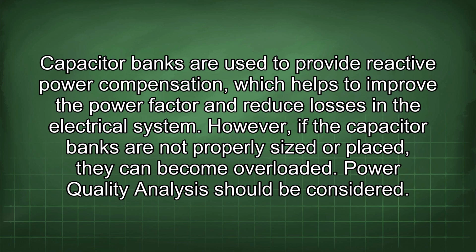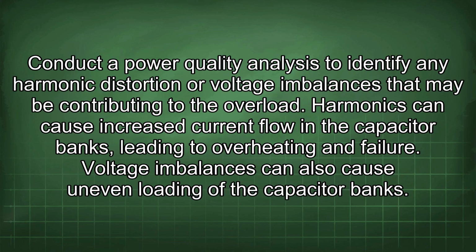Power quality analysis should be considered. Conduct a power quality analysis to identify any harmonic distortion or voltage imbalances that may be contributing to the overload. Harmonics can cause increased current flow in the capacitor banks, leading to overheating and failure. Voltage imbalances can also cause uneven loading of the capacitor banks.